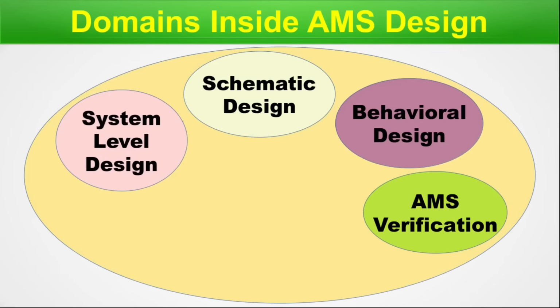Both the simulations happen concurrently and with the exact same time step and time scale. Whenever needed, handshake happens between the two. One thing to emphasize: at the analog digital boundary, proper A to D or D to A converters have to be properly configured. Thus, transaction between analog signal and digital signal happens without any errors. For this stage, you must have skills on industry standard AMS tools such as Virtuoso AMS, Xcelium ADMS, Custom Sim, VCS from the three major EDA tool vendors.